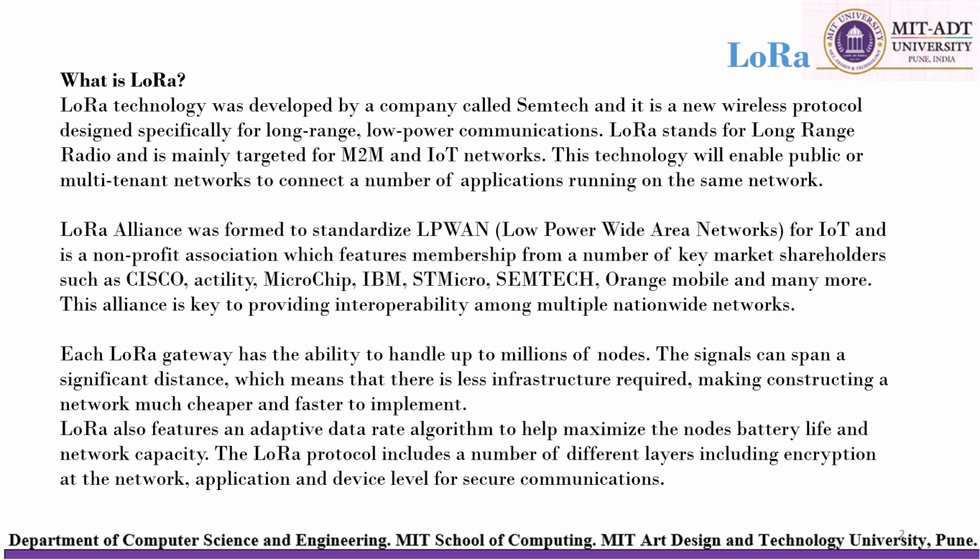This technology is quite robust against disturbances, and we can have long range or long distance data transmissions. Basically, LoRa modulation is based on chirp spread spectrum technology. LoRa is very much ideal for applications that transmit small chunks of data with lower bit rates.